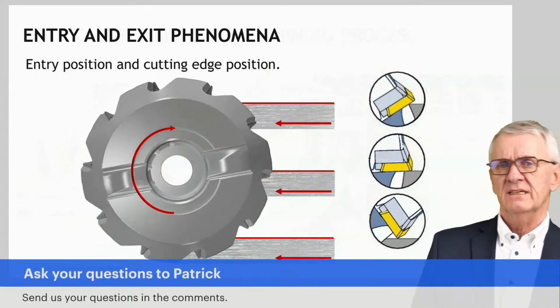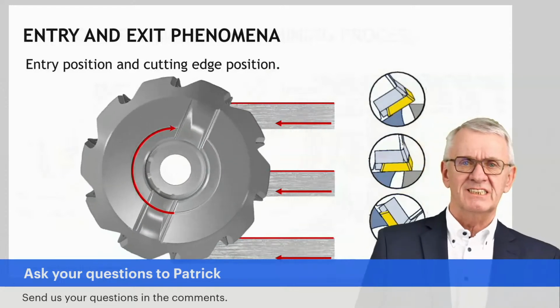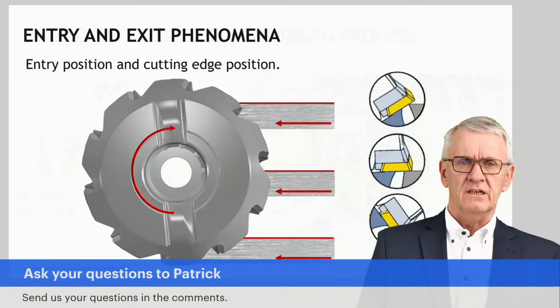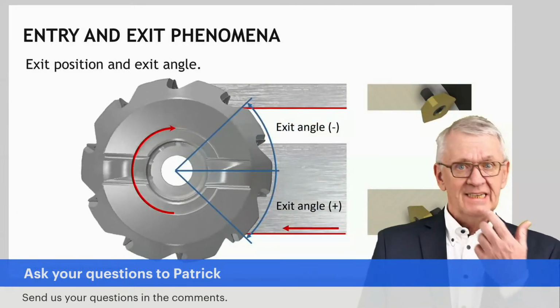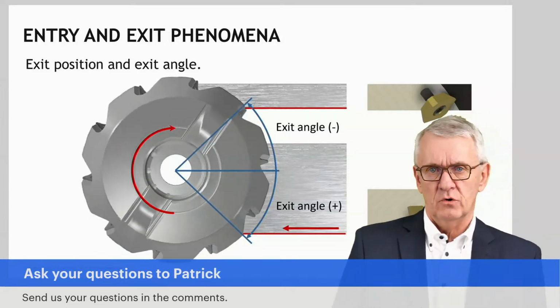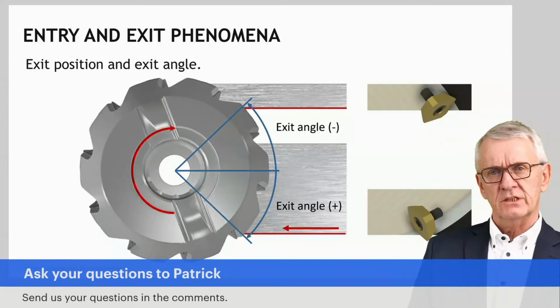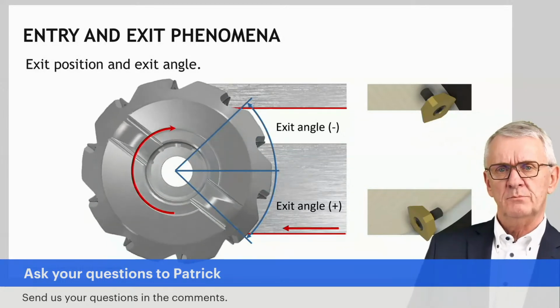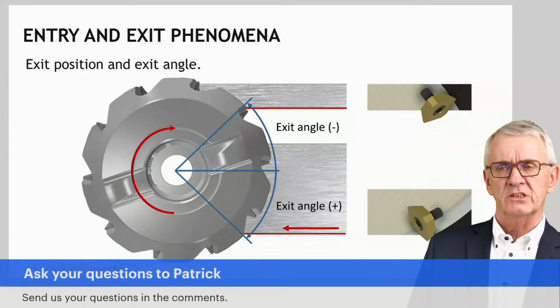With side milling, up milling or side milling, down milling, the situation is less risky. But in general, entry phases nowadays are not so critical anymore, as long as you follow instructions for correct cutting conditions. Normally present carbide grades can handle impact situations.